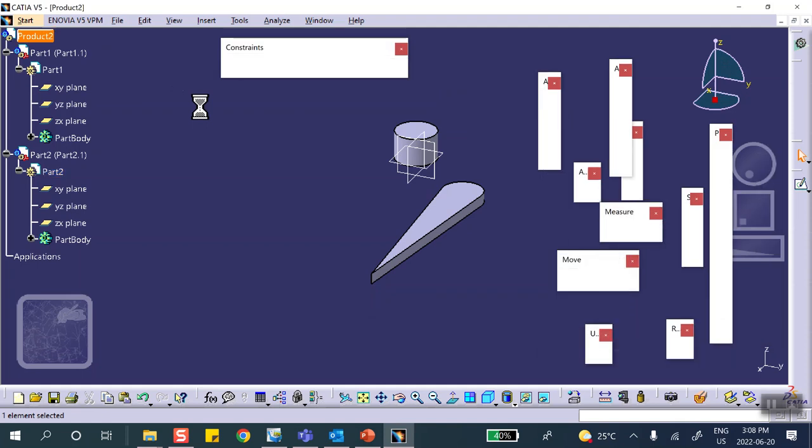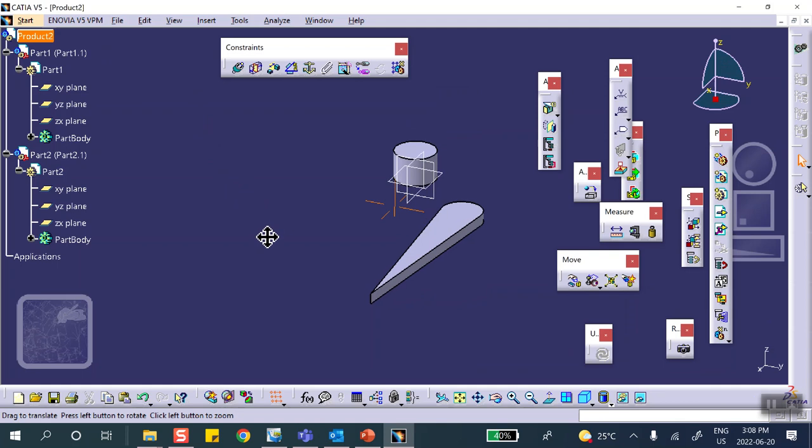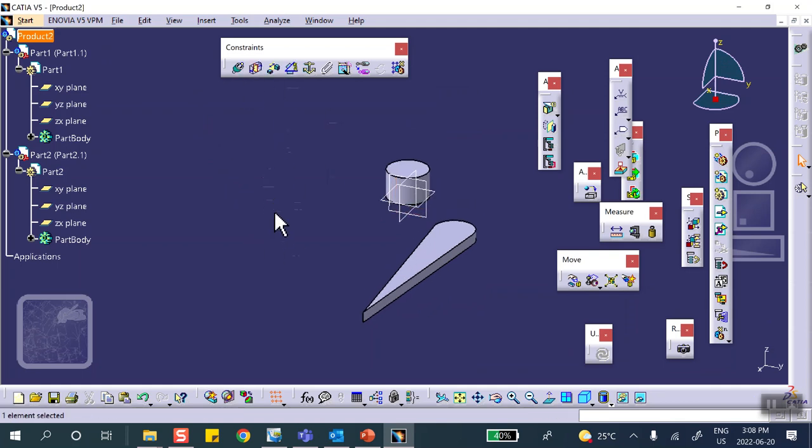Now, because you are not using the magic wand, you really don't have to put assembly constraints here. But I would like to fix something in space. If I don't, then when I try to make the joint, it's going to say, "Hey, nothing is fixed. You want to fix it there." So actually, you know what? Let me not do this. But I'm just telling you that if I fix this thing, anchor this, I will not get this message that you see later on. It's all right.